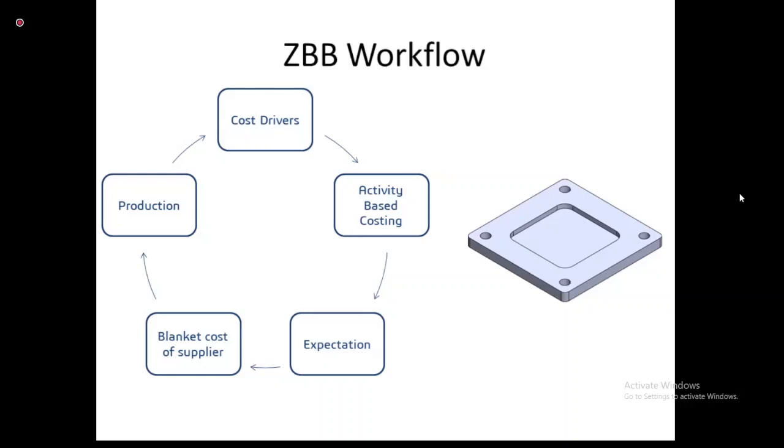More technical cost drivers are machining hours, the number of engineering change orders in the manufacturing drawing, the machining setups required for production, the number of inspections, or the direct labor working on this component. There are n number of activities involved in this product, so I have to shortlist which cost drivers are affecting the product price.